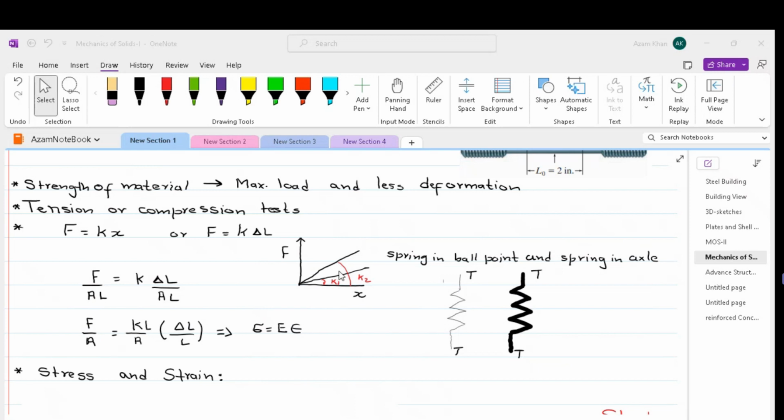This thought experiment clearly shows that the force is equal to stiffness times extension curves can be different for the same material. Therefore, we have to normalize the forces and the extensions or elongation within this equation. It is because of this reason that we convert the force elongation curves to stress strain curves.